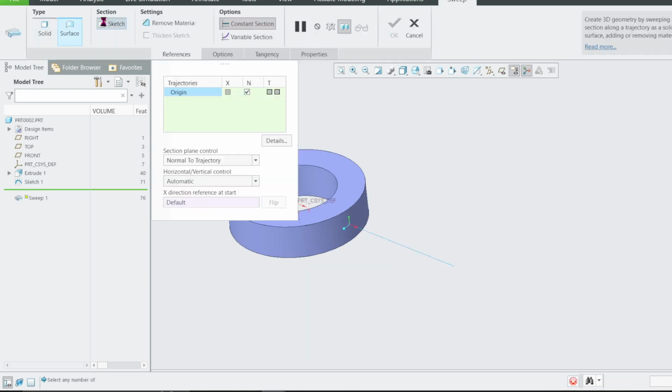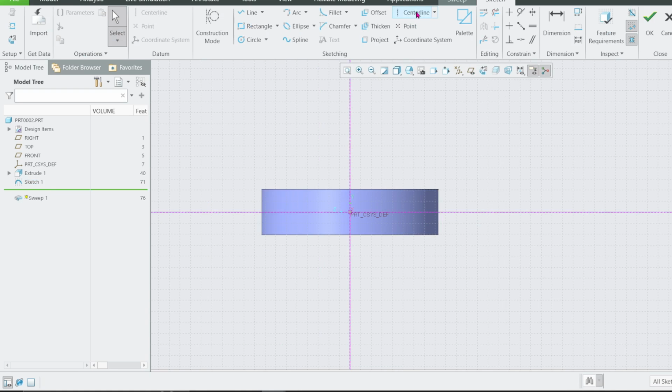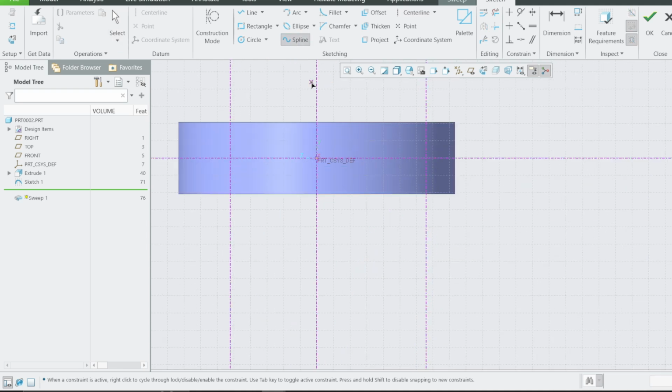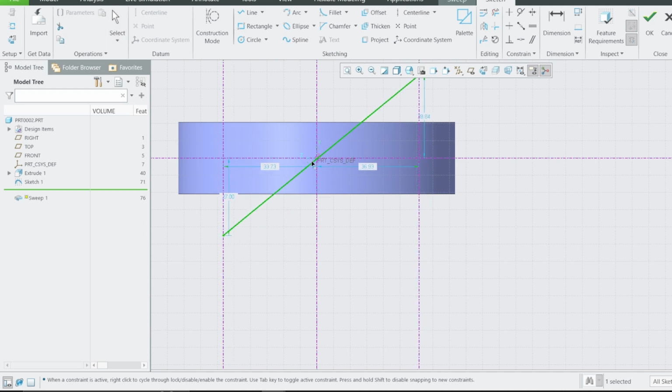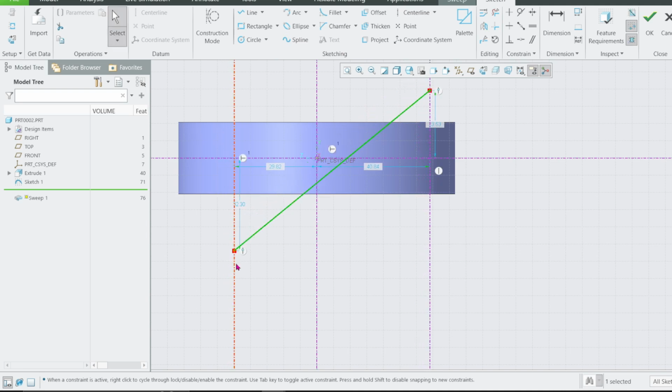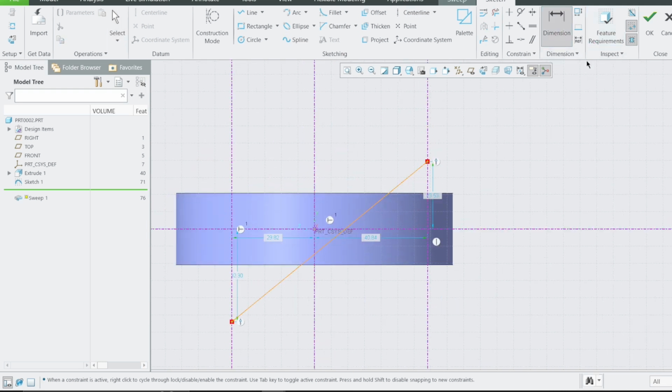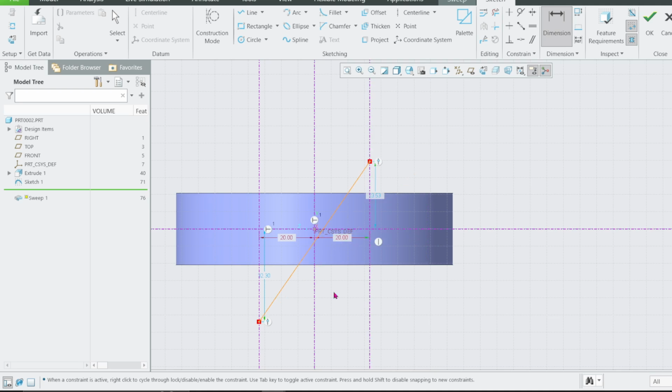We're using a surface sketch. I'm going to drop some center lines. I'm a big fan of center lines, by the way. I like using center lines where possible, especially when I'm using line. That is the profile. When you view from this side, that is the profile. And I want now to drop some dimensions here. Let's say the initial cross section to be 20 and 20.